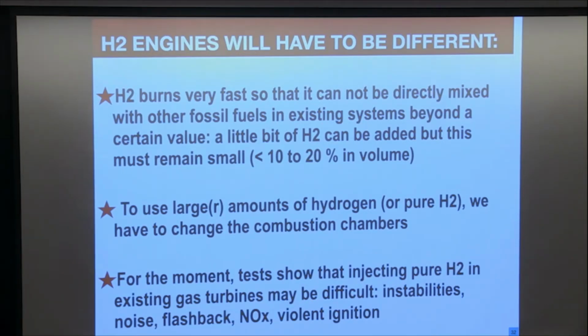Why? Well, because usually you have problems of thermal loads on the wall, or you get into combustion instabilities, as you've seen yesterday. You also make a lot of NOx. I will explain later why. You can have violent ignition, which I talked about yesterday. It's not easy to ignite an engine with H2. You can have surprises. You can have flashback. I've shown you examples too.